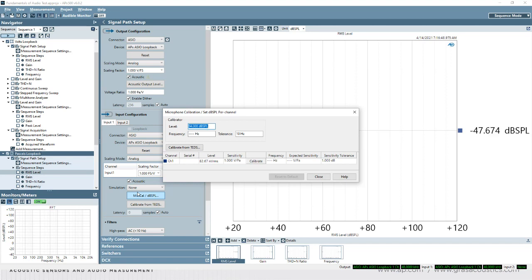And in our analyzers, in some location, there is a place for us to enter the ratio, or we commonly call it the sensitivity of our transducer, which will tell us the conversion from pascals of sound pressure to volts, so we can then express it in our software and look at measurements in the domain of pascals. But really, the analyzer itself is measuring volts.